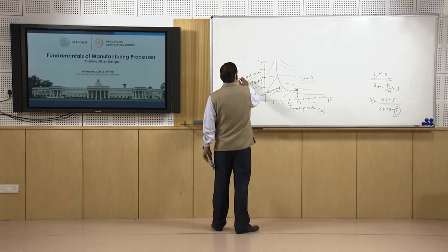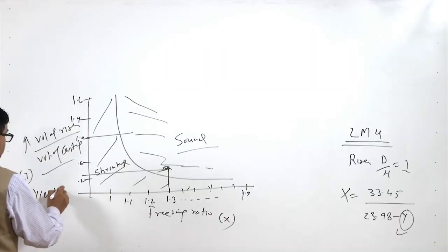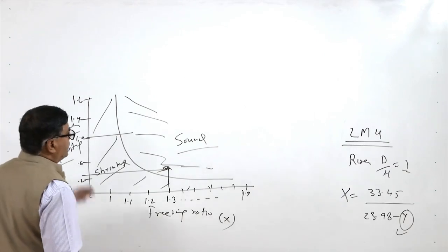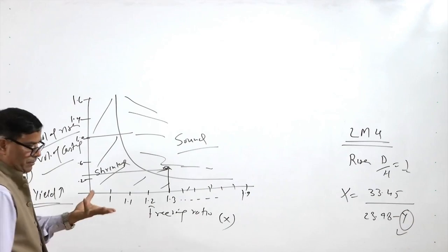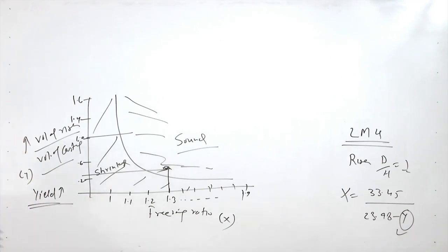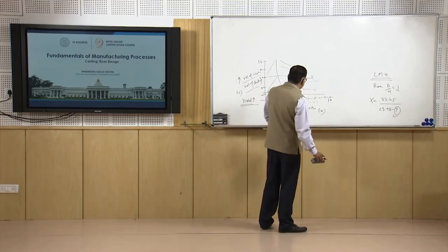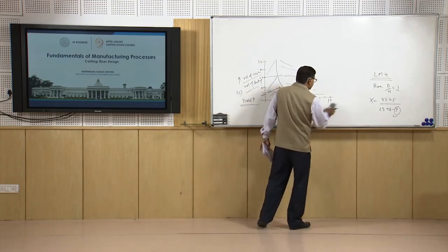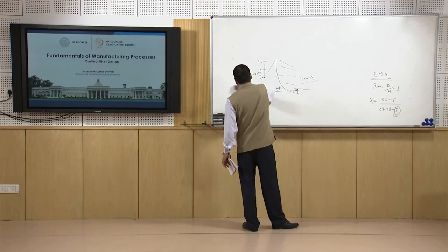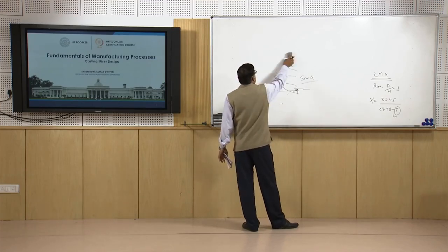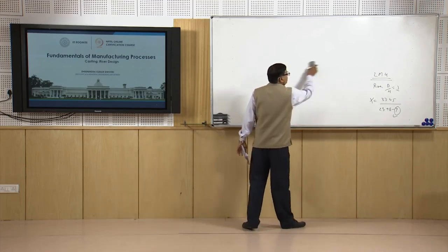So, if this ratio is low for sound casting, then definitely our yield will be much better, because the molten metal being solidified in the riser will be less compared to the volume of the metal solidifying in the casting. So, efforts are always made to have better freezing ratios, for achieving high yield through a low riser volume to casting volume ratio.